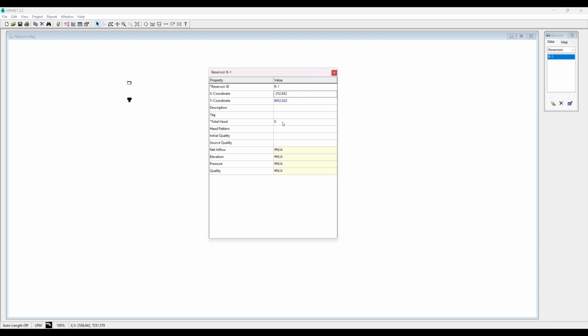If you set the elevation or the total head, let's say it's at 100 feet from our zero, whatever we want our zero to be, say it's 100 feet above our datum, so it's going to provide 100 feet of head, and you can't run out of water. So that's how EPANET assumes reservoirs operate.